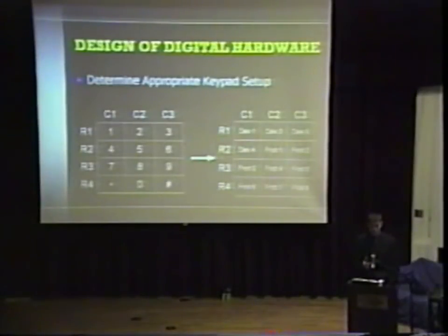Before designing the digital hardware, the input requirements needed to be set. Basically, the input is a standard telephone keypad. From that, 4 device keys were set up for the first 4 inputs. Those 4 unique inputs basically translate to a 2-bit digital word, and the remaining 8 function keys translate to a 3-bit digital word.